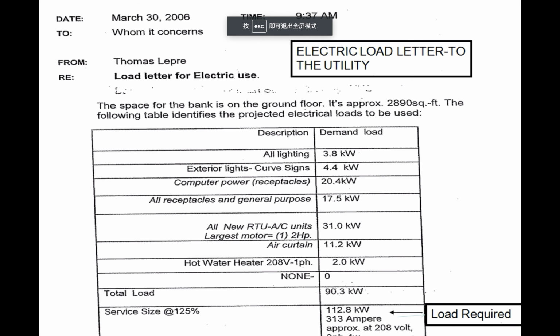you add a certain percentage to it. So in this case, they add a 25% factor to it, and that's the request that they made. They said, I need 112.8 kilowatts to be able to come to this building. Con Ed will take a look at that, find out where their closest source of electricity is, bring it out to the closest point of their system to your facility, and then tell you here's where you have to come. Con Ed would monitor the connection between that line box and wherever your breaker panels are, and from that point you have to distribute it into your building.